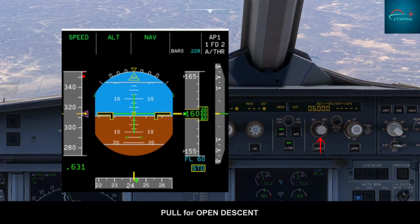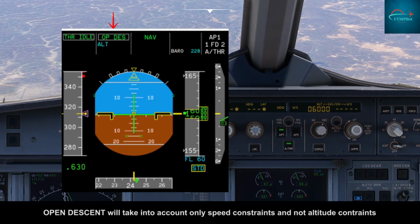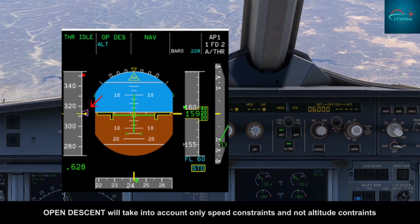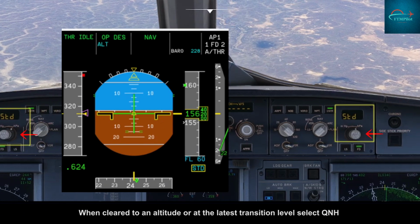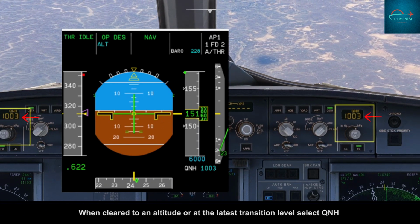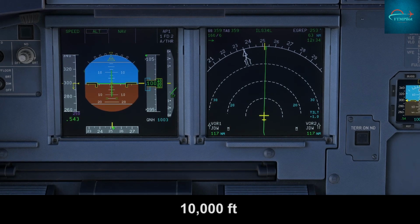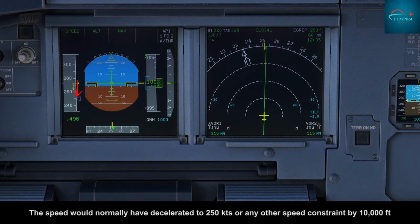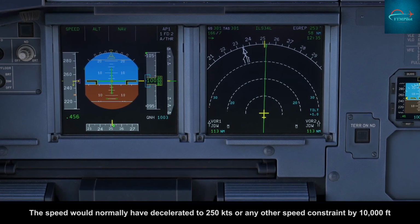Pull for open descent. Open descent will take into account only speed constraints and not altitude constraints. When cleared to an altitude or at the latest transition level, select QNH. 10,000 feet. The speed would normally have decelerated to 250 knots or any other speed constraint by 10,000 feet.